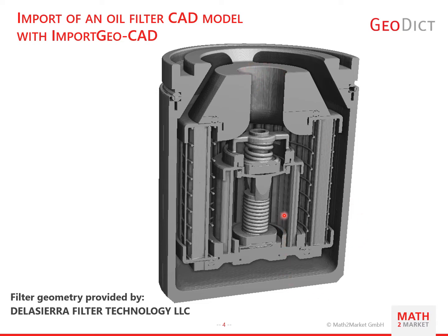You can also see an inner pleat here, and also a valve, which in this image is closed. But the valve is designed to open when the oil filter becomes clogged through the outer pleat, or when the oil is too thick, for example at low temperatures in winter.